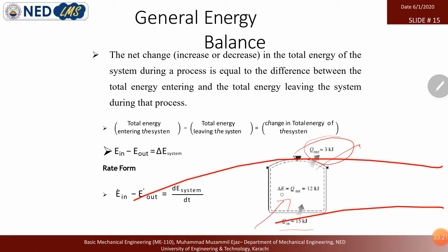The internal energy depends upon the total internal energy, as in the closed system when it is not moving or not gaining elevation. So heat transfer increases its internal energy, so we put it with the positive, and when heat is lost from the system, its energy will decrease, so we put the sign convention minus.